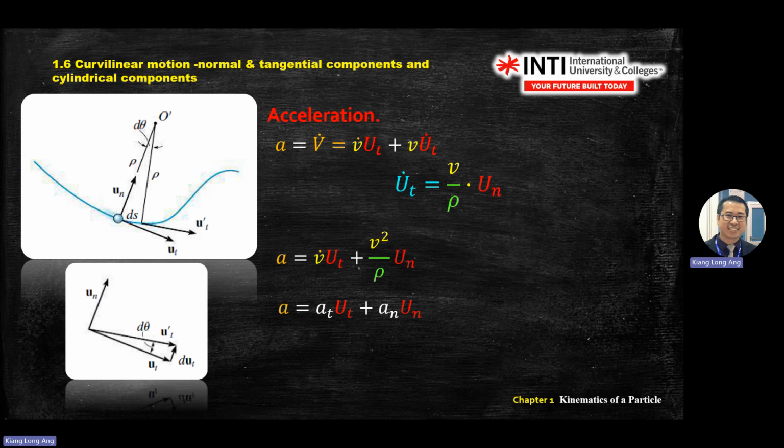This is direction. Why link to the rho? Because normal pointing where? Pointing inside the normal. This is your rho, this is your R. So you can't go wrong. Normal is the radius, so rho inside the equation. Tangent means the velocity that you learned previously, always tangent to the curve. So you won't go wrong. If you confuse these two, then the rest calculation will be wrong.